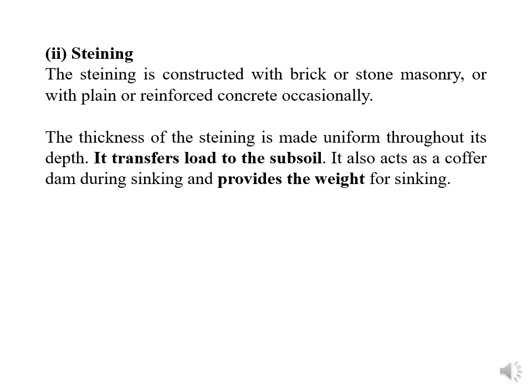Weight for sinking. We have to maintain the thickness of the steining in such a way that by its own weight it will start moving inside the earth, right? Definitely the laborers are going inside the well and excavating the soil from the edge of the well so that the well will go inside the earth easily.